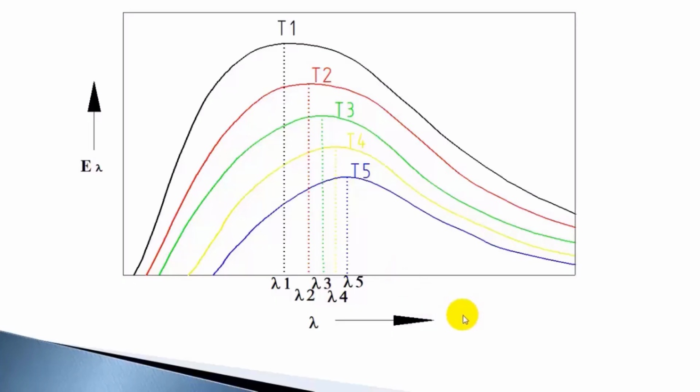And we can also prove this, whatever value is given by Wien's displacement law. At the peak, the slope of this curve is 0, and this distribution is as per Max Planck's distribution law. So we have Max Planck's distribution law, which gives how the curve is varying, how the distribution takes place. For that equation, if you differentiate and equate to 0, you will have a slope 0 here. Max Planck's distribution law depends on two values, temperature and wavelength.